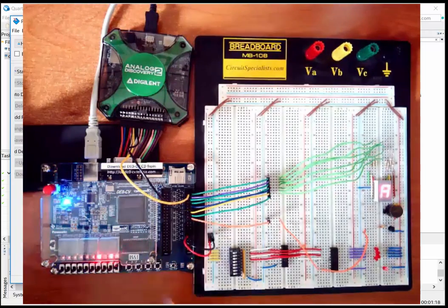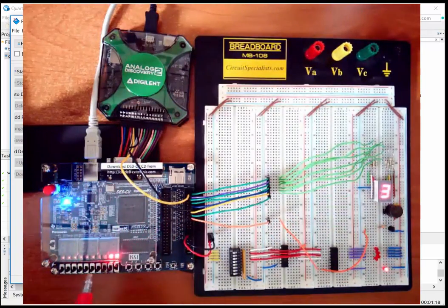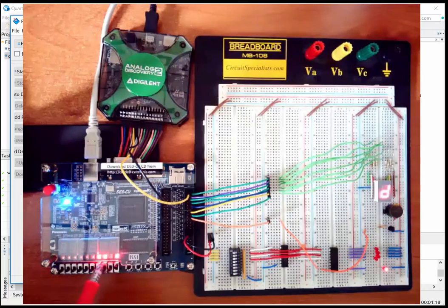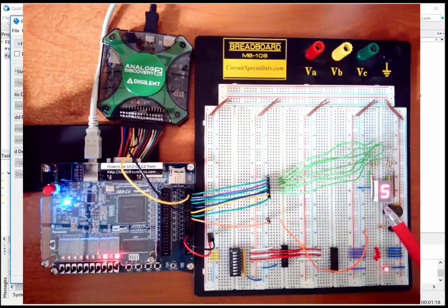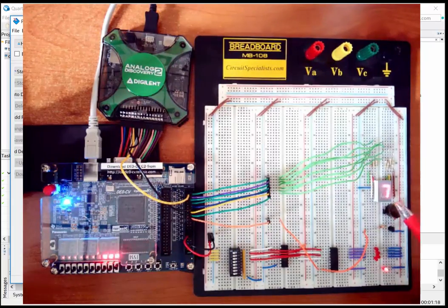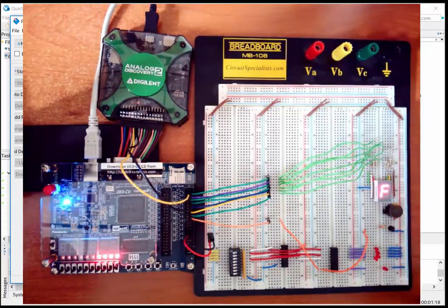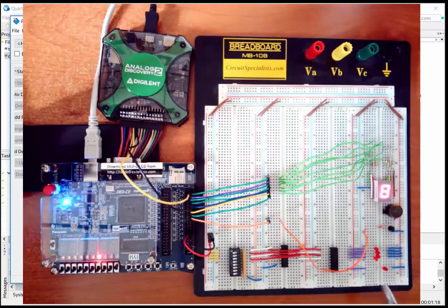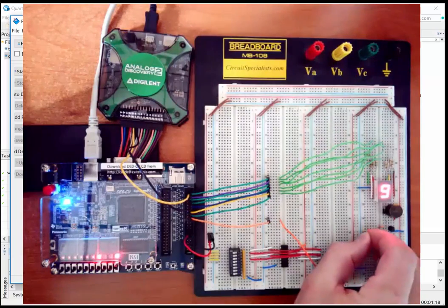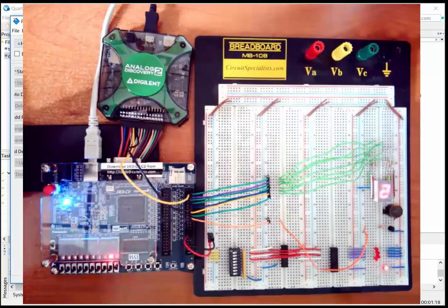We have the clock coming in. We have the 4-bit outputs, the 4-bit counter value of the finite state machine, displayed on the red LEDs. We have the hex symbol of that displayed over here, and you can actually see it counting now. So 0, 1, 2, 3, all the way up to F and it rolls over. Notice also that every prime number asserts over here, and I can turn on my buzzer if I wanted to do that too. So every time a prime number comes by, the thing beeps.